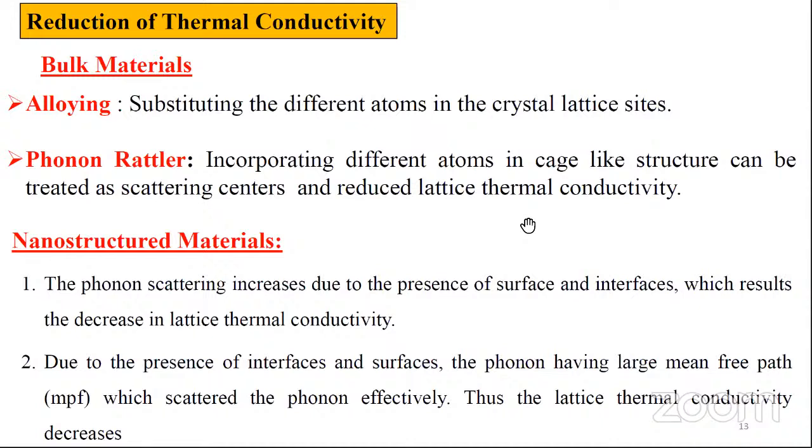So there are some conditions for the best thermoelectric materials: degenerate semiconductors, semi-metals with carrier concentrations of 10^18 to 10^20, semiconductors with band gap approximately 10 kT, and materials containing heavy elements are considered good thermoelectric materials.